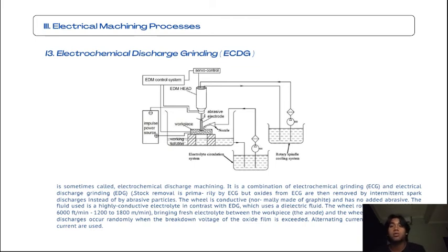So the process is used for grinding of carbide cutters, and it can also be used with hardened tool steels, nickel alloys, and parts that are heat sensitive or fragile, such as tiny columns and other fragile parts. It is advantageous because they are finished free from burrs, and stresses from grinding are avoided. Forms can be ground if the wheel has a profile.